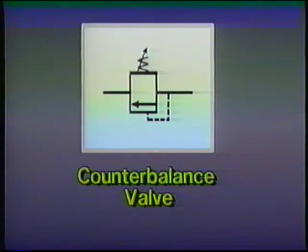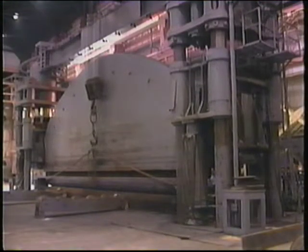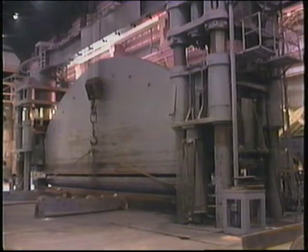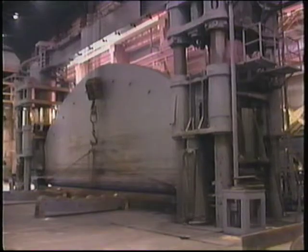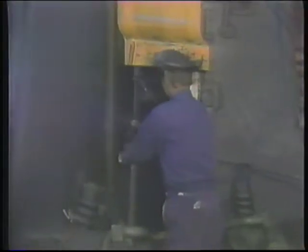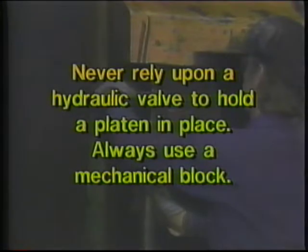For example, a counterbalance valve is often used to control the movement of the platen on a press. Dies bolted to the heavy platen form metal parts as the platen is pressed into a workpiece. Platens often weigh several thousand pounds, and they must always be mechanically blocked whenever they are not being used. Never rely on a valve to hold a platen in place.